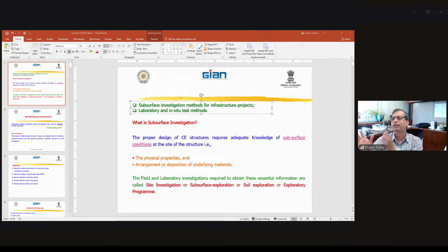On the other hand, for CPT, you just push it into the ground and you will get the result automatically. But you cannot use it in totally gravel type of materials. You cannot penetrate, so that is the disadvantage. And it will give you everything, it will give you a graph. If the cone penetration end bearing is higher, it is sand, or more sandy or cohesionless soil. If the sleeve friction is more, it shows on the computer screen itself automatically.